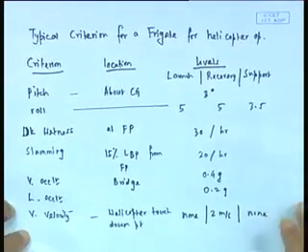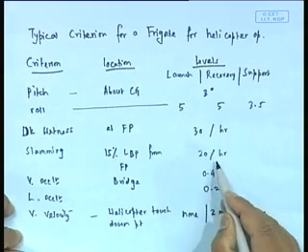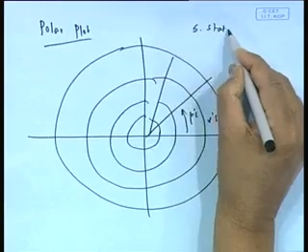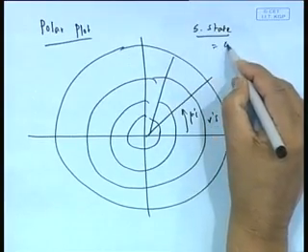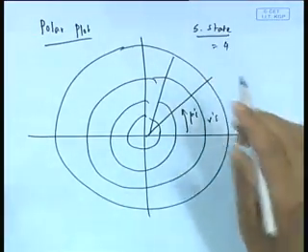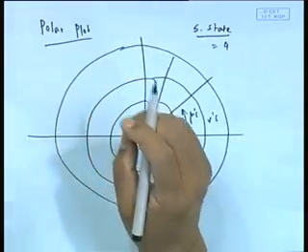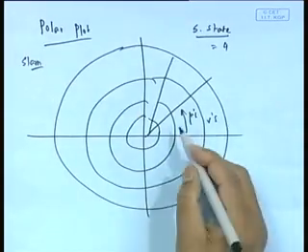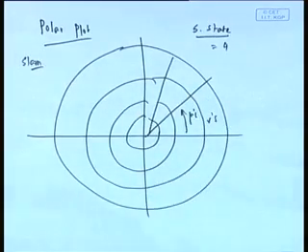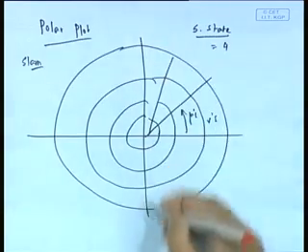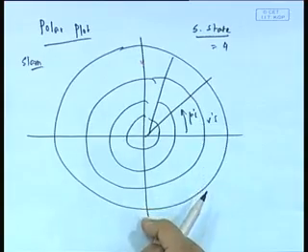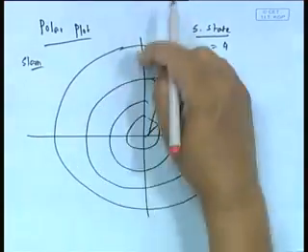What you do is that people will find out, let us take an example. Bottom slamming at a given location should not exceed 20 per hour. Okay. Now, you find out, this is for a given sea state, say sea state equal to 4. You have to repeat that for different sea states, and this is for a particular response, say slamming. So, what you find out is that slamming 20, there is a boundary there. This is actually say 0 degree here and this is 180 degree here, you start from 0, 90, 180 like that, this is the angle.